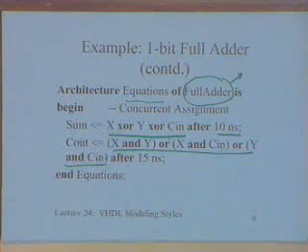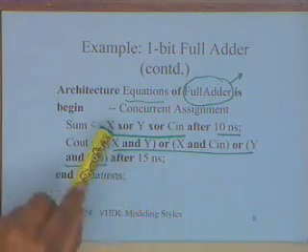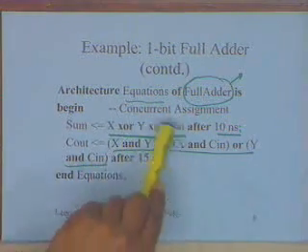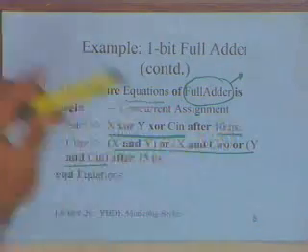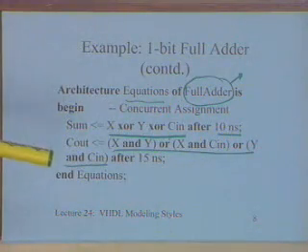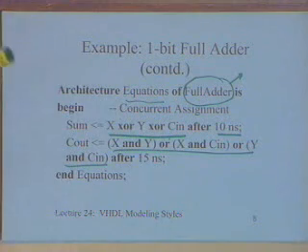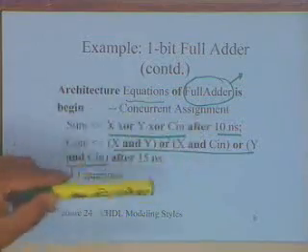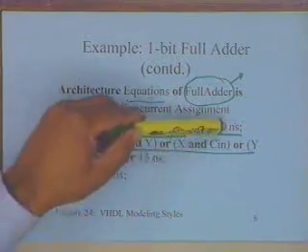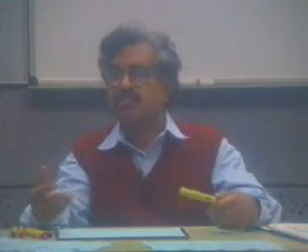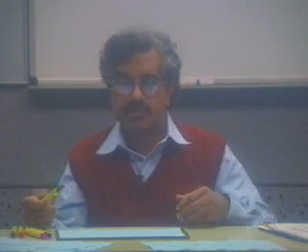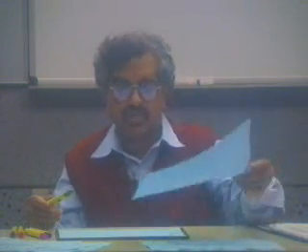Let's say I have to synthesize this statement. What it means is I have to choose components which will give me a delay of 10 nanoseconds, which is not possible. That's not the role of the synthesizer. After you synthesize, you can get the delays depending on what you are synthesized with, but you do not specify this for synthesis. You can only specify the Boolean equation and not the delays. But delays are what VHDL provides for modeling, if you have already synthesized it, or you are going to just study the models of delays, and how the system will perform under those delays in a simulation model.